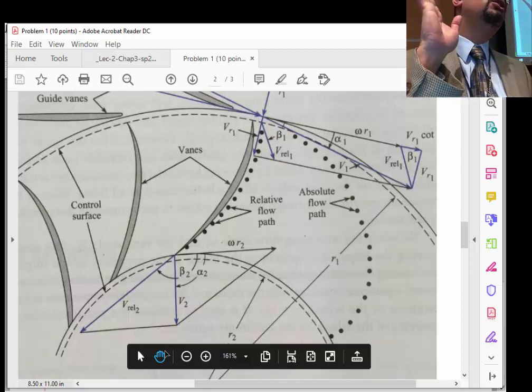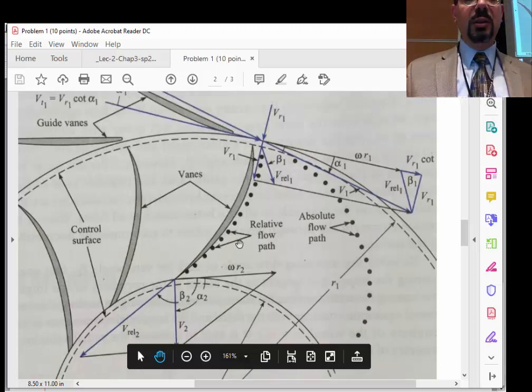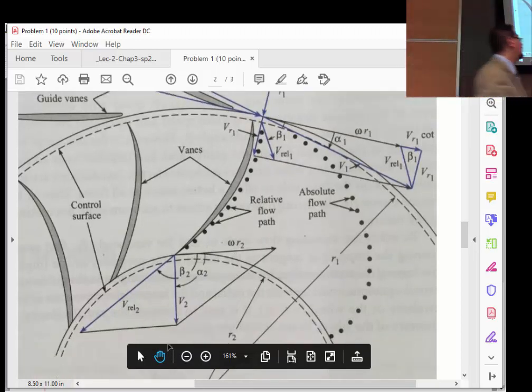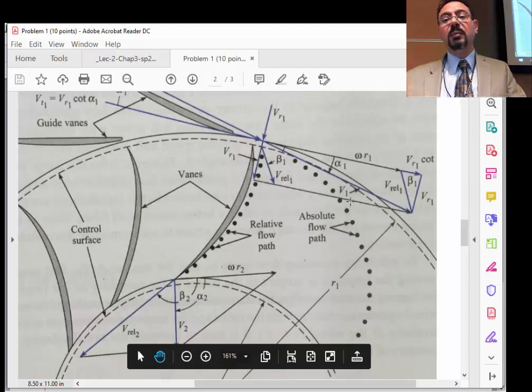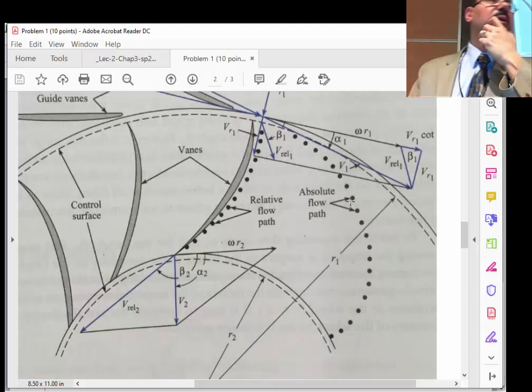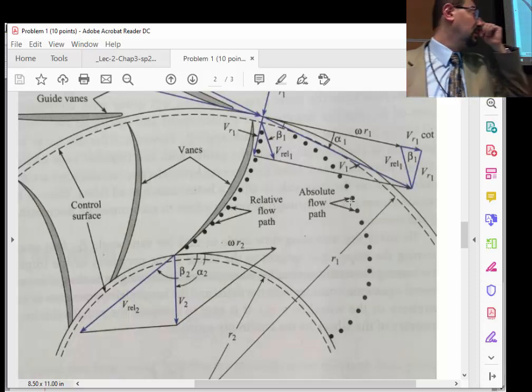So that we consumed all the tangential momentum that we generated from V1. So you leave all radial, right? So the equation for the torque would say m dot R2 V theta 2 is 0, right? There is no V theta 2. We left all radial, right? Minus m dot R1 V theta 1, and look how much V theta 1 we got. So huge V theta 1, huh? Huge V theta 1, and almost 0 V theta 2. Okay? Make sense? Very good.